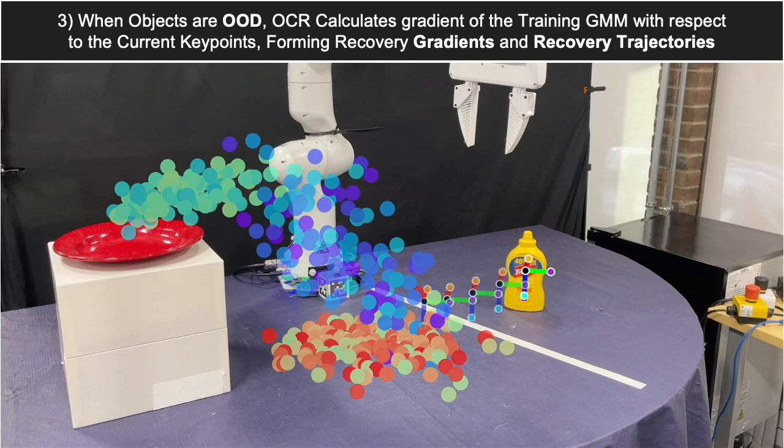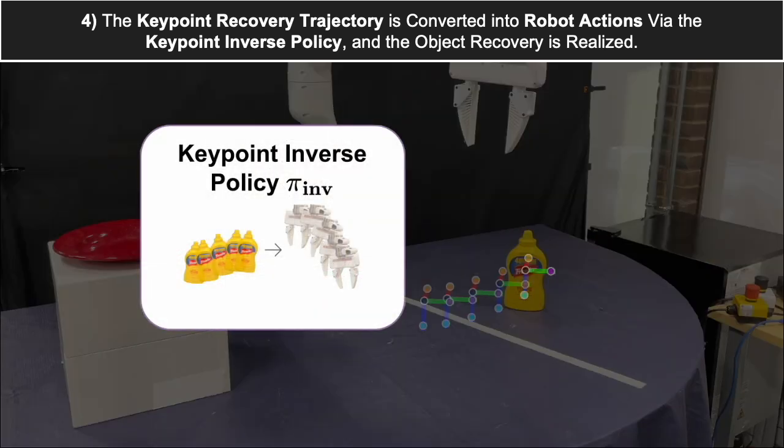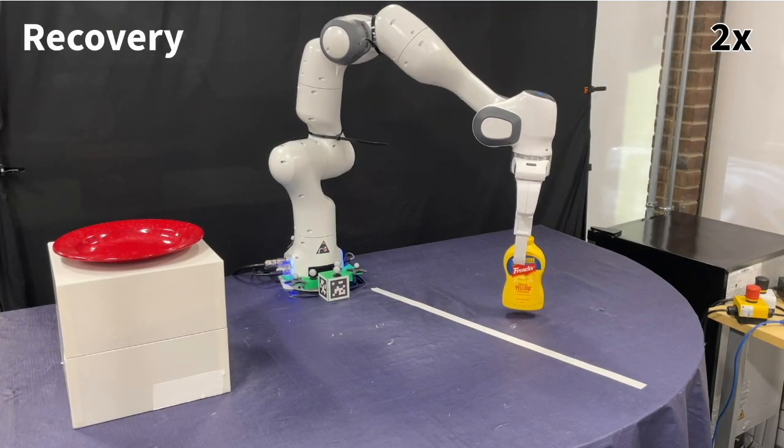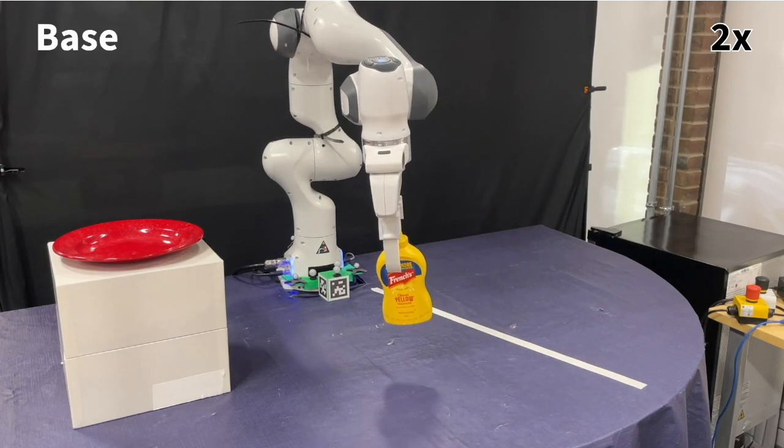Lastly, using the keypoint recovery trajectory, we obtain the robot actions by calling the keypoint inverse policy. The keypoint inverse policy takes in desired keypoint motion and translates it into the robot actions necessary to complete those keypoint motions. This inverse policy is learned purely from the object and robot interaction that existed within the base training dataset. Using the OCR framework, we can now recover from unseen object out-of-distribution scenarios without the need for additional data collection.